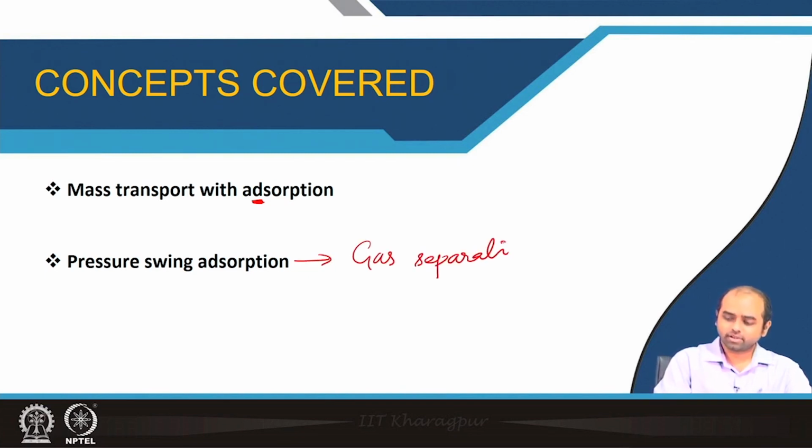In the case of liquid separation, the process does not change by altering the pressure. In that case, you have to pass a regenerative solution through the bed, so that the bed can be reactivated, all the bound molecules are released, and the bed is regenerated. That is a slightly more complex process. In the case of gas adsorption, if you just alter the pressure or apply vacuum in the same column, it very quickly gets regenerated.